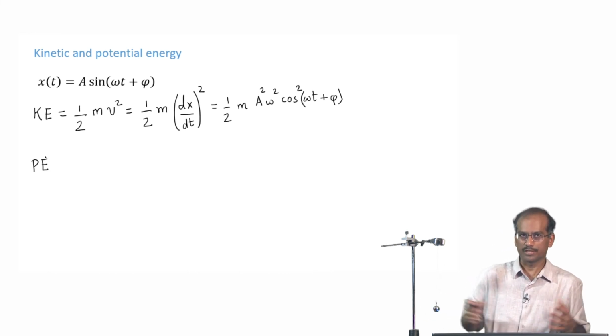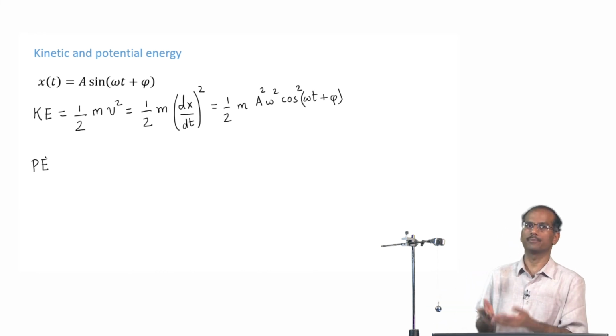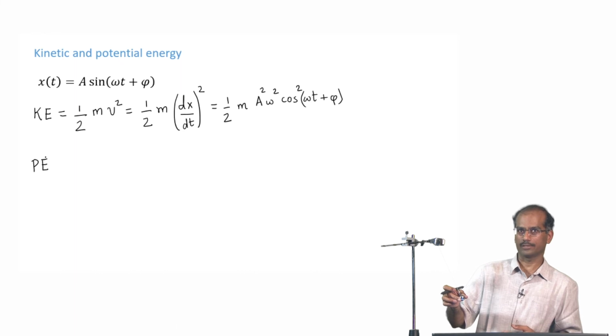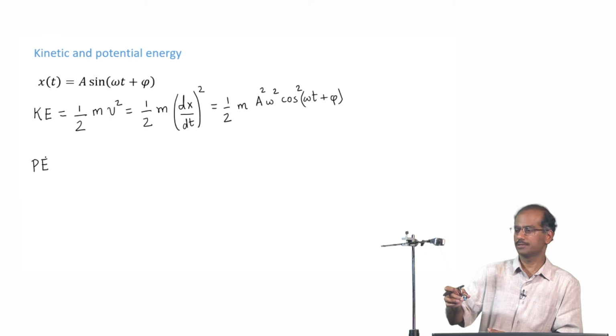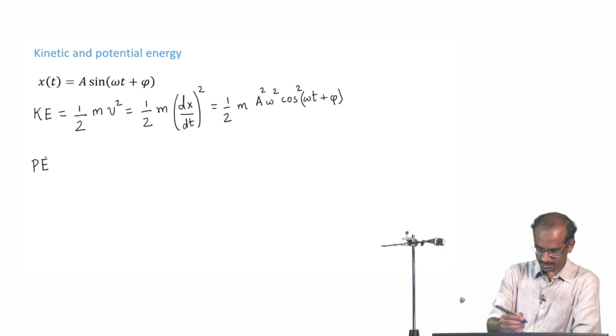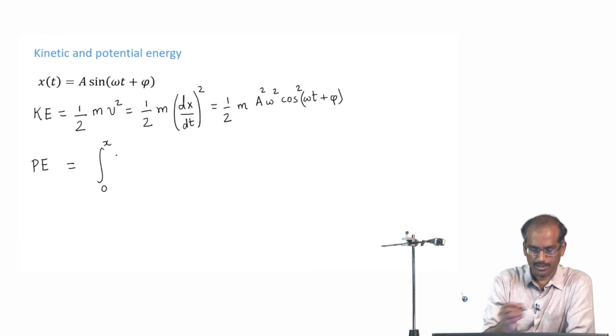So, this is its rest position, it has no kinetic energy because it is not moving, and it has no potential energy because we have said that at this point the potential is 0. And when I move it like this a little bit sideways, I am putting in potential energy, and the amount of energy is equal to the work done in moving it from here to here, and when I leave it, it will start doing its work. So, the potential energy would simply be equal to the work done against the restoring force. So, in general when I write in terms of the stiffness constant, it is S times x prime dx prime. So, I need to do this integral. So, remember that this was our restoring force.